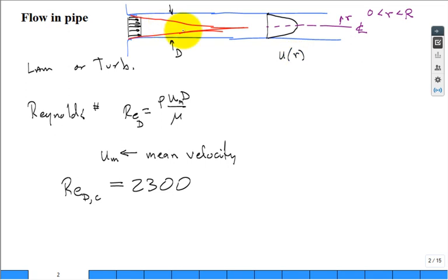But if we come back to this location, we sketch the velocity profile. It's like the middle part hasn't felt the presence of the walls of the pipe yet. It's still developing. And yet, we have a velocity profile that's flat in the middle and then like that. Again, this shape is if it's laminar fully developed flow. If it's turbulent fully developed flow, it's flatter in the core region.